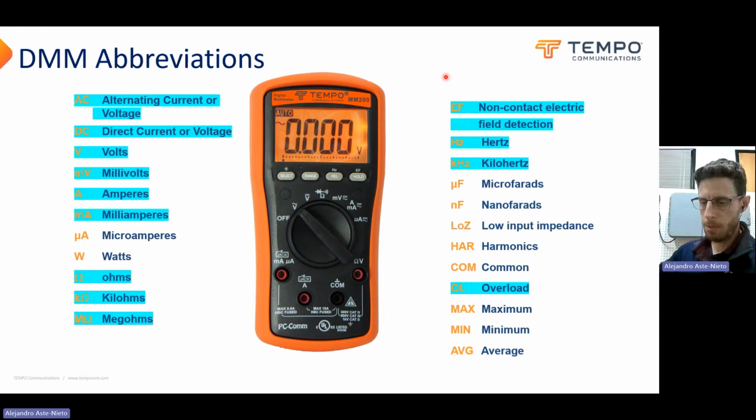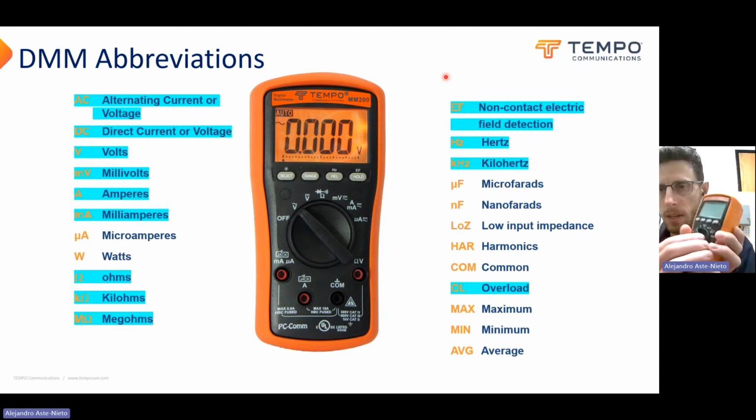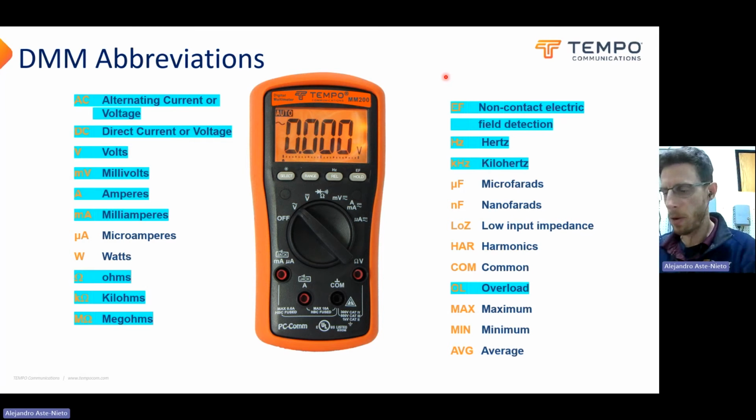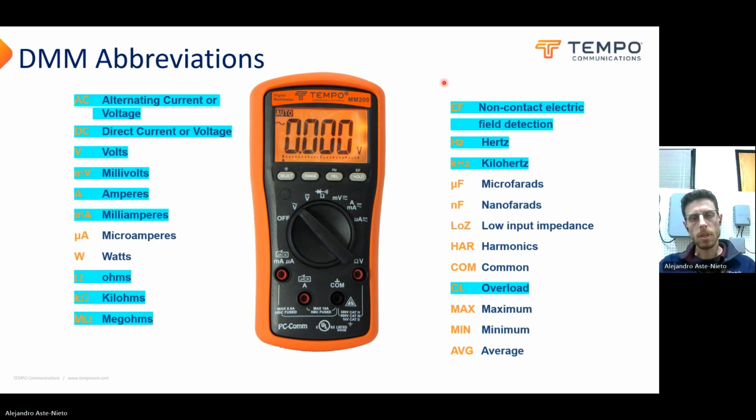These laptops do a pretty good job of canceling any non-voice noises. So I don't know if you'll be able to hear it, but we got a beep coming out of the meter. Yeah, I'm not sure if you guys are going to pick that up in the mic. And then this one, you just turn this on and hold the EF button until it goes to EF there. And this can be held up to a power source and let you know if there's AC voltage nearby.